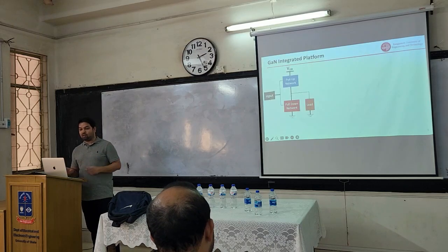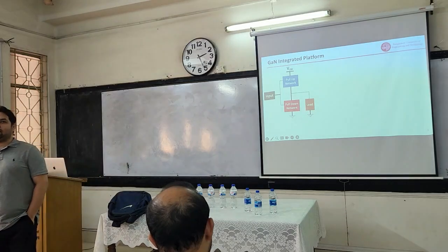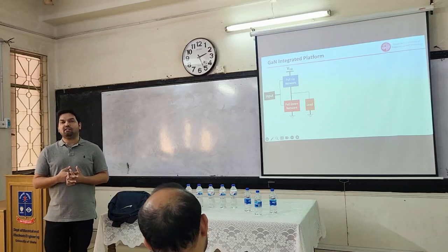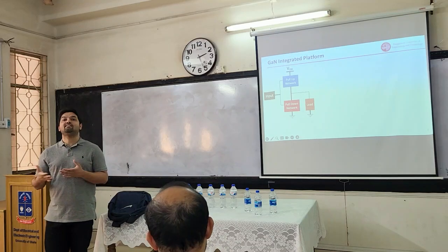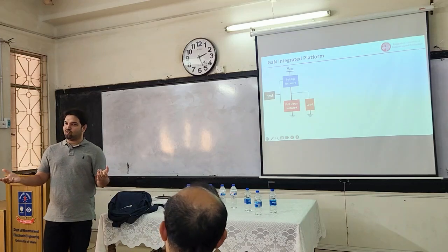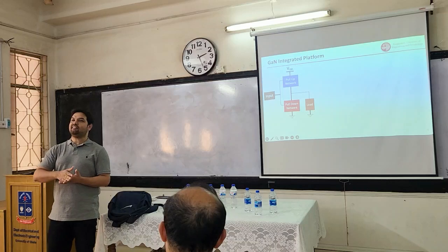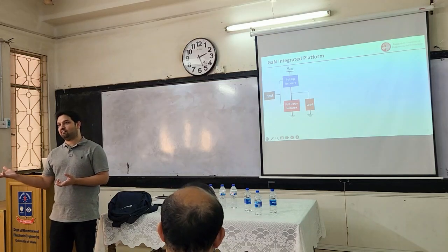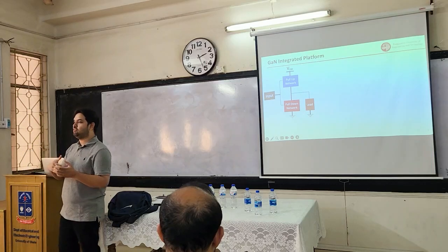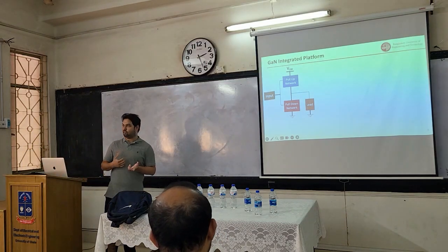Okay, so why do we need an integrated platform? Because without integration, you really cannot increase the complexity of the circuit. For example, in a power electronics circuit, you need a lot of sensing. You have to sense the current for overdrive, and you have to sense the temperature. Then you have to make a decision. So for sensing and decision making, you need logic. Without logic, you cannot do it. And for logic, you need a complementary network, so you need a pull-up network and a pull-down network.